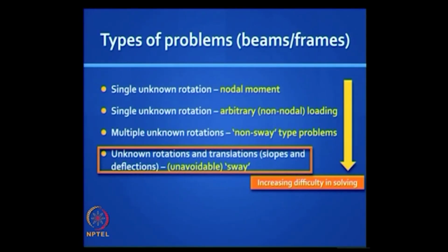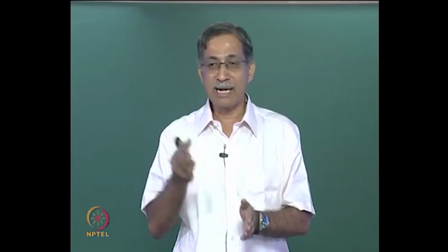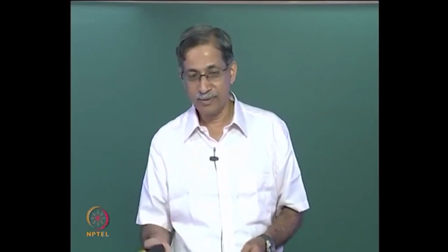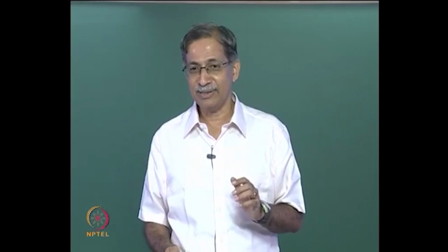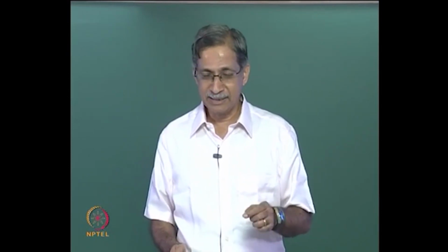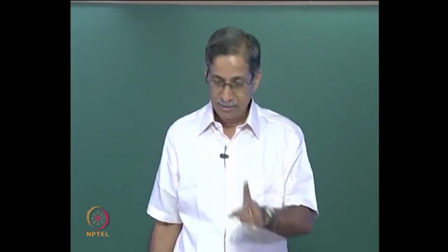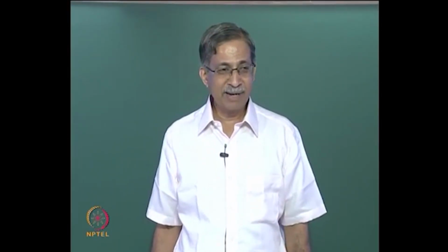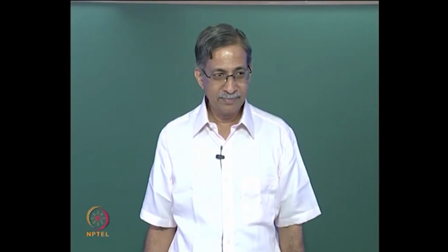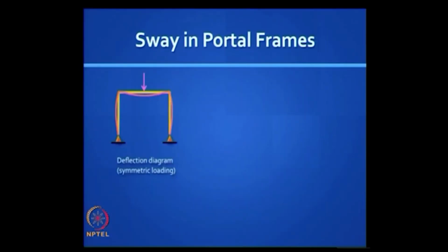Now we go to the 4th category, the toughest, that is when you have sway which you can't get rid of, it is unknown. It is not like a support settlement which is known, the chord rotations are unknown. In some cases you can take advantage of them. We will look at those cases in tomorrow's class. For the time being, let us look at how to deal with this. So if you have a symmetric portal frame with a symmetric loading, what is the deflected shape? Will it be also symmetric? Yes, it will be symmetric.